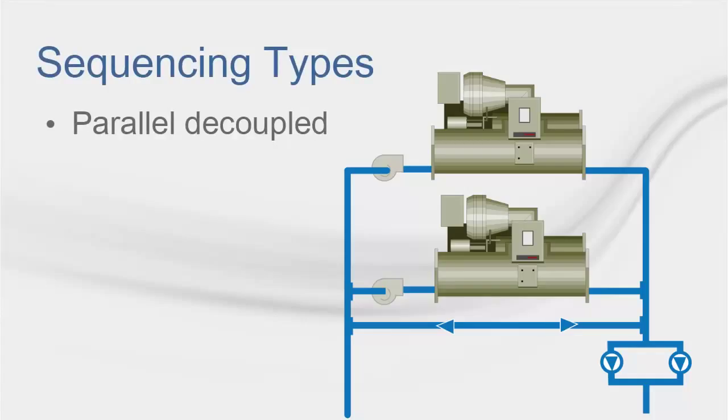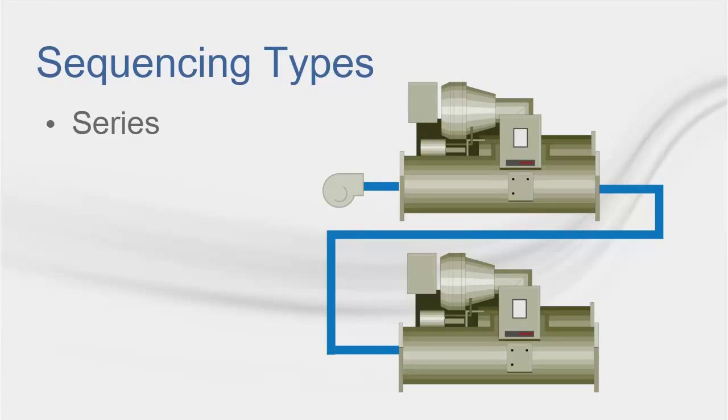This arrangement allows for constant flow through the chillers whenever operating, thus eliminating the potential issues regarding system and chiller flow rate or rate of change limitations that can result with the parallel configuration. In addition, all chillers that are operating are loaded proportionally, that is, in equal percentages, just like the previously mentioned parallel sequencing type. A series arrangement requires 2 or more chillers piped in a series configuration with the lead chiller handling the entire load until its capacity has been exceeded.